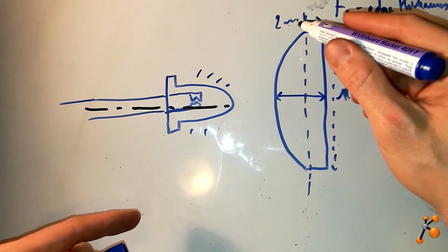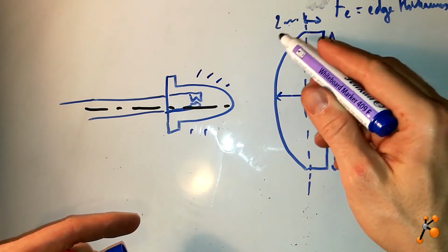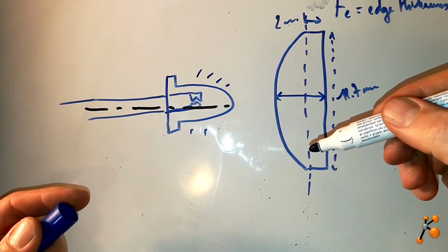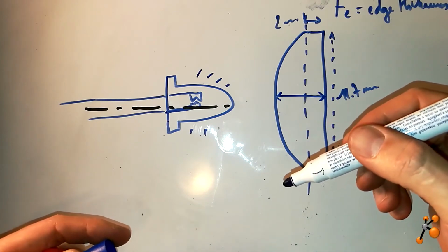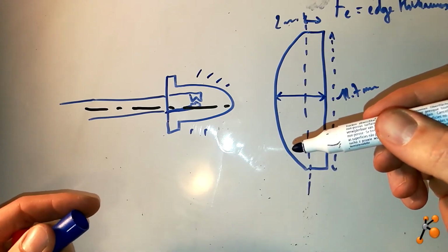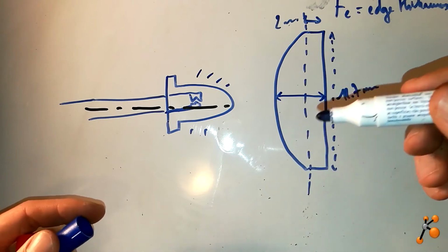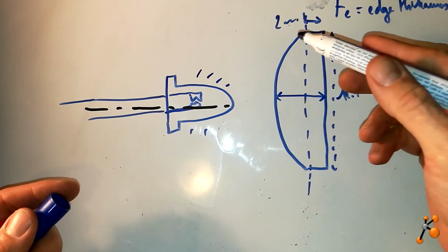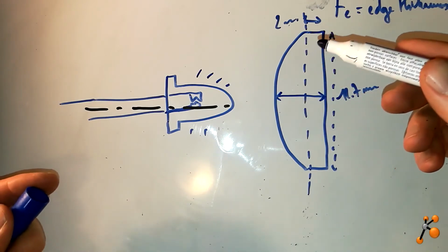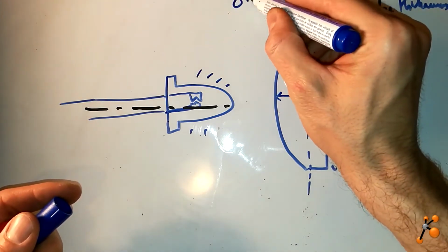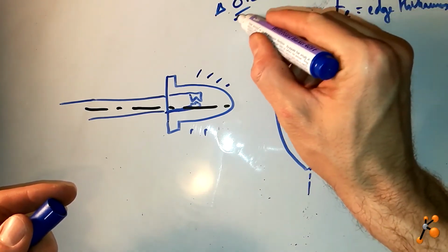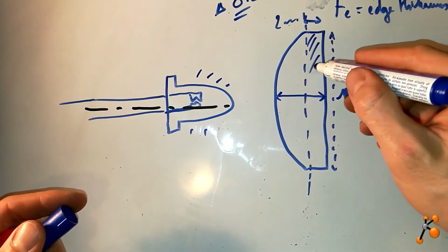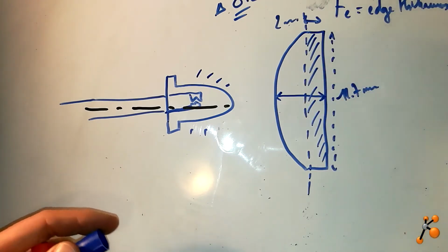So here we have 2 millimeter and not 1.8 because when you design something in AutoCAD or with 3D software, your 3D printer will not exactly make it as it should be. So 1.8 millimeter, I consider that you have 0.2 variation in dimension. So 1.8 to 2 it's the same. So let's say that this is 2 millimeter, this edge thickness.